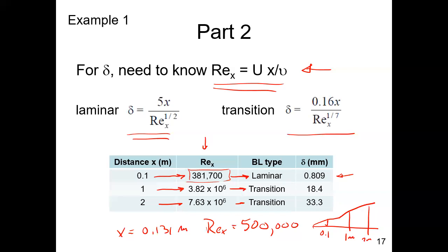In the real system, the fluid is sitting still, it's quiescent, and the plate is moving through it. And so what you see is the fluid sitting still, and at an instant where you take a snapshot, the plate's moving at 5 meters per second, and the velocity profile is going from 5 meters per second back to 0.